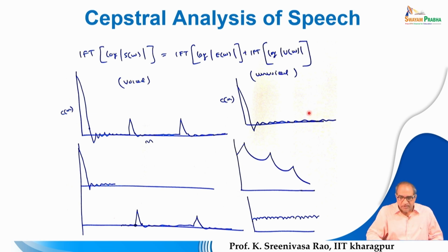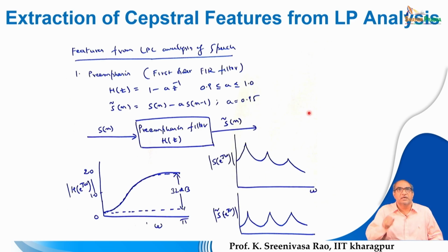So, here the next part we will discuss is the extraction of cepstral coefficients or cepstral features from the linear prediction analysis, because as you observe, the linear prediction coefficients that you determine from the linear prediction analysis represent the all-pole filter.